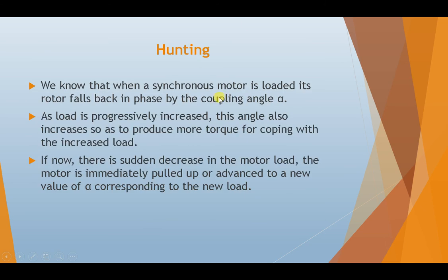Next is hunting. We know that when a synchronous motor is loaded, its rotor falls back in phase by the coupling angle alpha. We already studied that whenever there is an increase or decrease in load, the angle between the rotor and the rotating magnetic field changes.